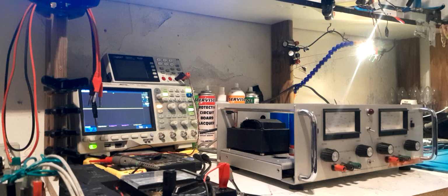And then I think just start compensating everything with a blanket approach. So basically large values of R's and C's to start out with, filtering op-amps, going from the output to the negative inputs, RC's across the inputs, stuff like that.